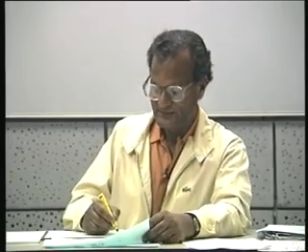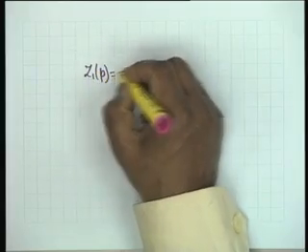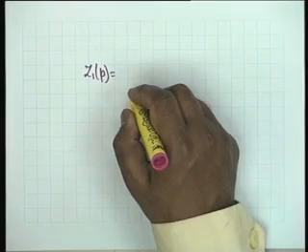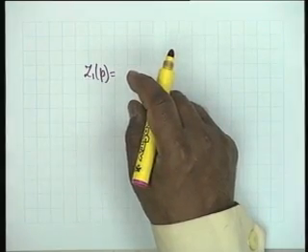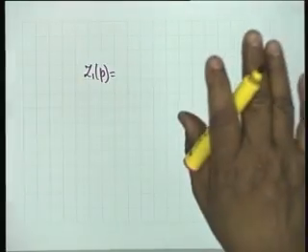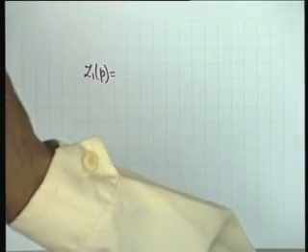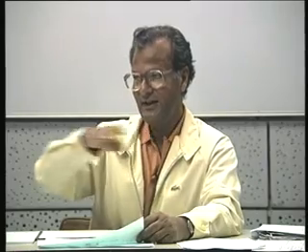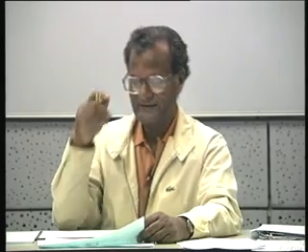Let us see. Z1 of p, have you understood the philosophy of this? Why did it occur? Because the poles and zeros were on an axis parallel to the j omega axis. Similarly, had we been given poles and zeros on a line parallel to the real axis, negative real axis, we could have done an RC or RL. This is a very popular question.